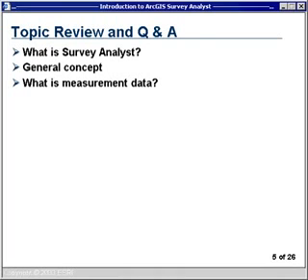In fact, you can COGO in survey data into Survey Analyst, and I'm going to show you an example of that here in a few moments. But basically, what is COGO, first of all? Well, COGO stands for coordinate geometry. Coordinate geometry are software or procedures that are used to enter measurements such as bearings, distances or lengths, and angles to resolve or define locations of points on, above, or below the surface of the Earth.